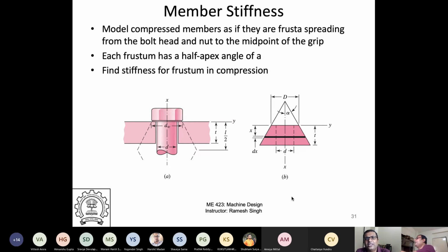So in this case, what is happening is the compression which the bolt is doing. This is just the compressive stresses, so material properties don't come into play. So you will have a very symmetric distribution, starting from highest pressure at the bottom and at the top, and just in the center you will have a nice broad area. So you will have kind of two inverted frusta.